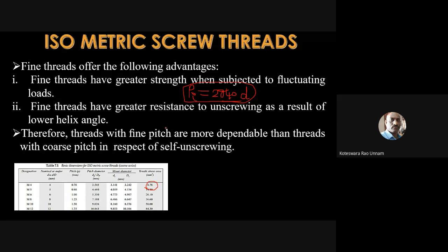So you have a pre-stress. This is what we call the pre-stress condition. That means before applying the load to the joint, there is a stress in the bolt because of the tightening of the joint. That we call stress due to initial tightening, or pre-stress. So that is one kind of load.